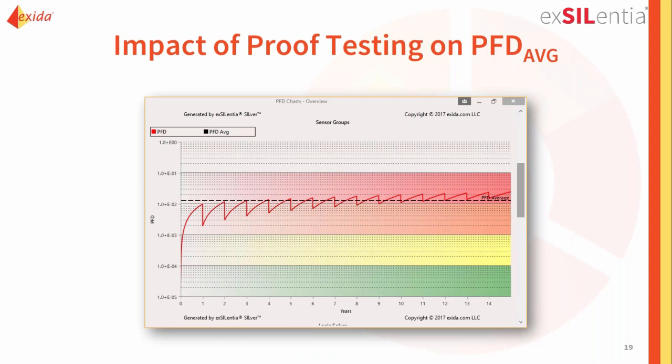And what does that do? Well, you've probably seen a similar chart where we see PFD as a function of time increasing. If we would not do any testing, this chart would just simply keep going up, and eventually we would reach a probability of failure of 1. But because we do proof testing, we will detect failures, and we will go back. The probability of failure will reduce, and we get a new sawtooth, so to say.